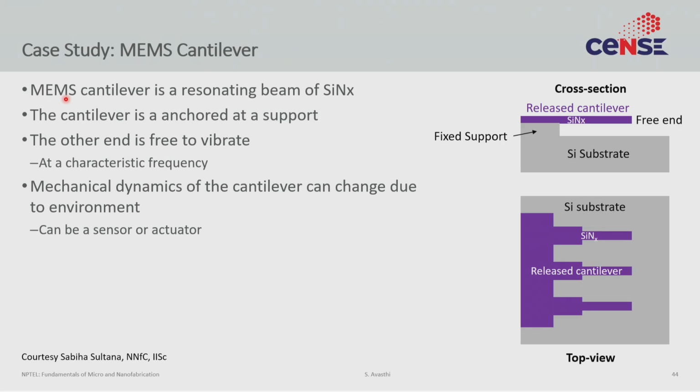The cantilever we shall focus on in this course and in this lecture is the MEMS cantilever, which is on the order of microns. So this is what we intend to make. We have a silicon substrate, an overhang, and this fixed support. We have to figure out a way to do the silicon nitride etch, to define the silicon nitride.